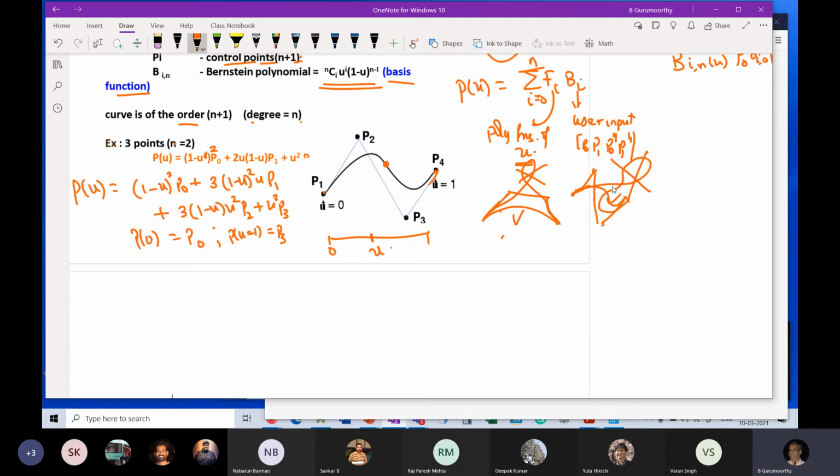And likewise, same thing here as well. So for these 4 control points, let me just change the color so it helps. For these 4 points, which are the control points that I had taken, the control polygon is that. And that is why we are sure that the curve has to be like this. It takes off in this direction because the tangent here is like this. It has to come back in this direction because the tangent here is like this. And it cannot go outside this box, and therefore this is the only shape that it can take.